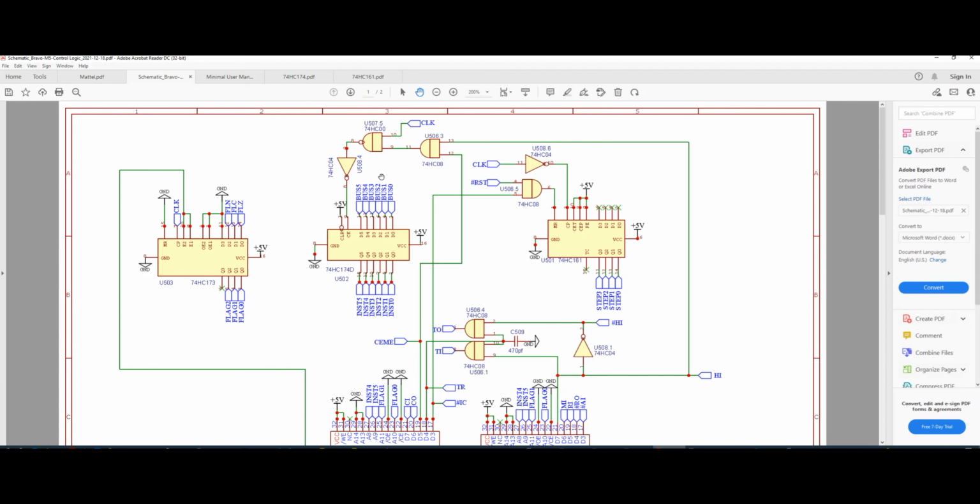And that's pretty much true about all 8-bit computers that you are probably familiar with, including if you have built Ben Eater's 8-bit computer. We were actually inverting the original clock pulse because we want that instruction to be read into our instruction register before the next clock pulse. So with that, I hope it is clear that the control signal is II, and the clock signal coming here is inverted before getting into that chip.